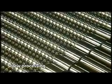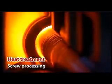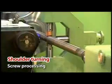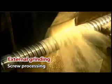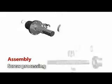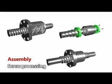Screw processing. Thread turning. Heat treatment. Shoulder turning. External grinding. Internal grinding. Assembly. Although the structure looks simple, the difficult part of manufacturing ball screws is that mechanical processing must be accurate to within a micron.